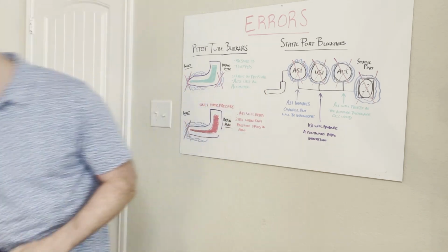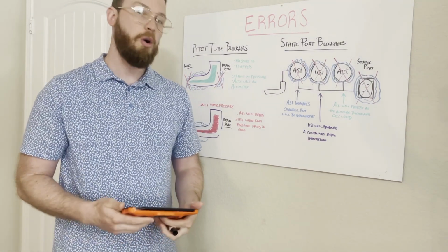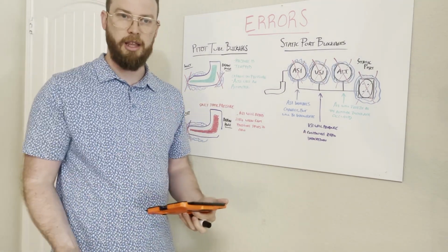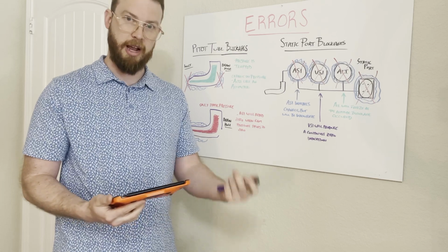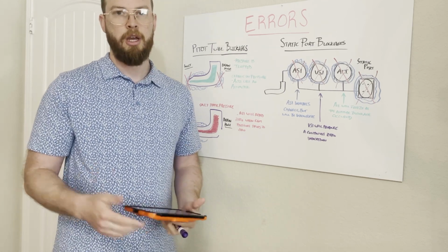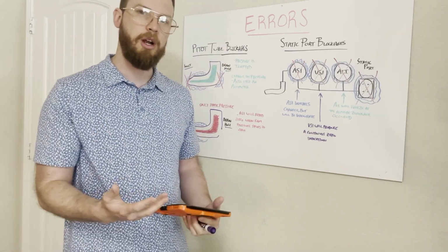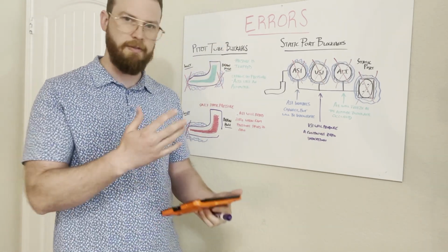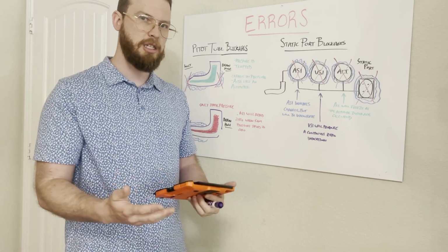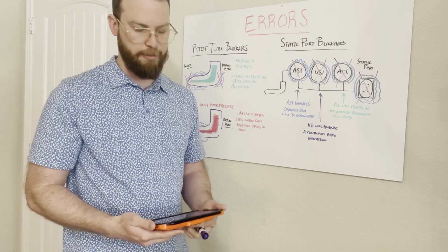Now, lastly, we have some preventative measures to go over that if we were to encounter something like this, we need to correct them and mitigate them as quick as we can, safely of course. So first thing is very important to cross-check all of our instruments and know our instrument indications, and constantly verifying and using these instruments as tools to know if something's a little bit out of the ordinary.